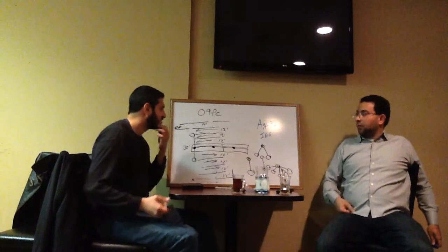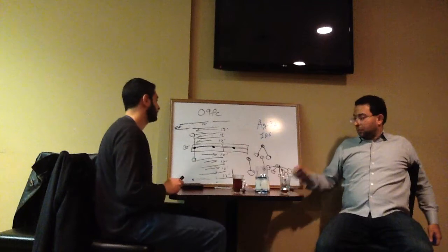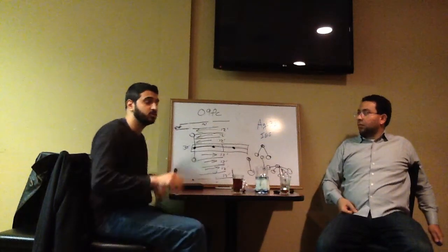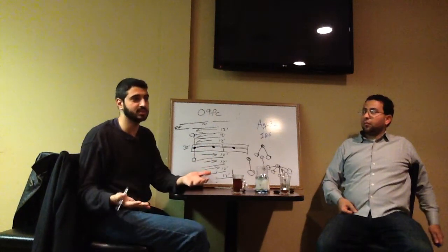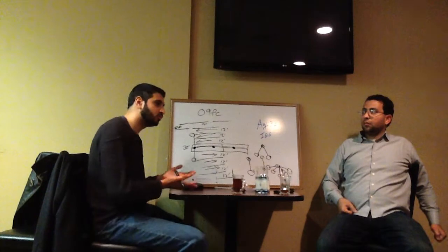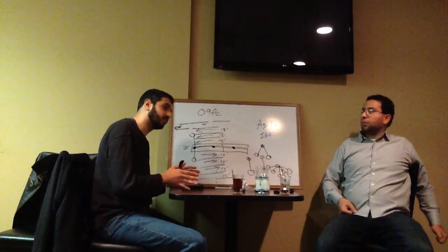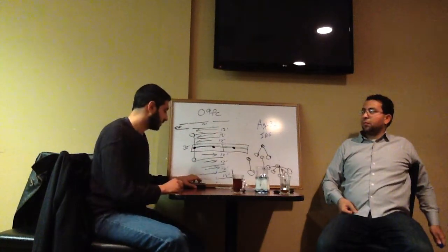So now what you have to input is the mounting height. The higher you go, the better distribution you get, but as Zeki said, the lower the intensity is. So you have to find the balance between the height and the power, or the wattage.